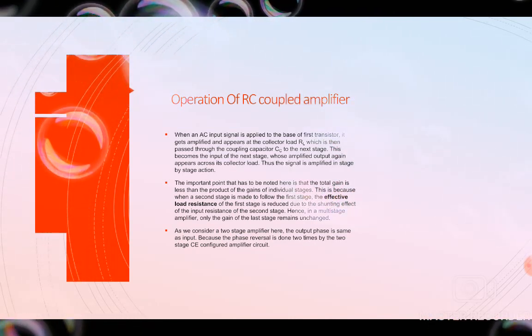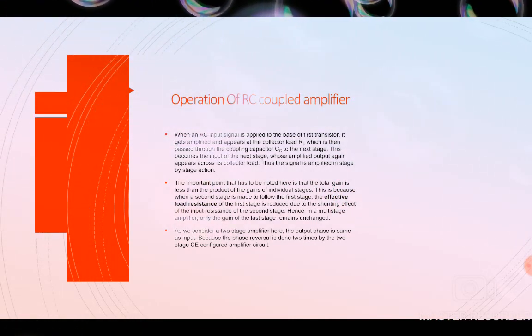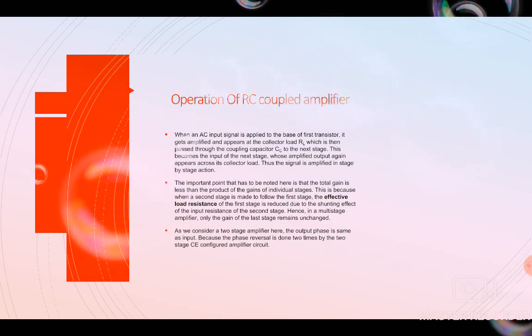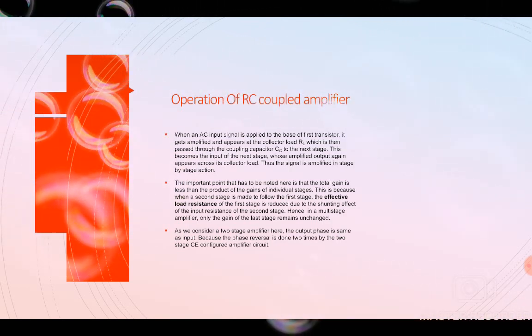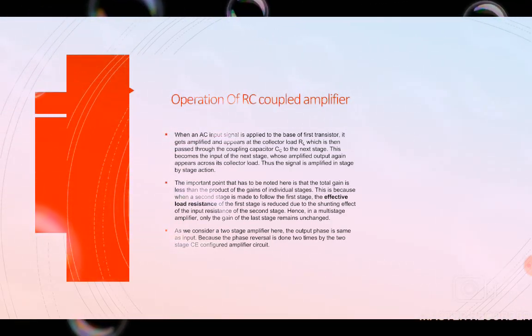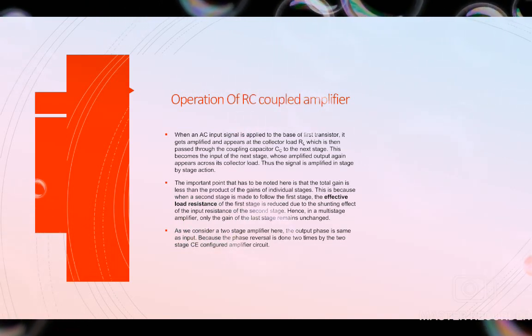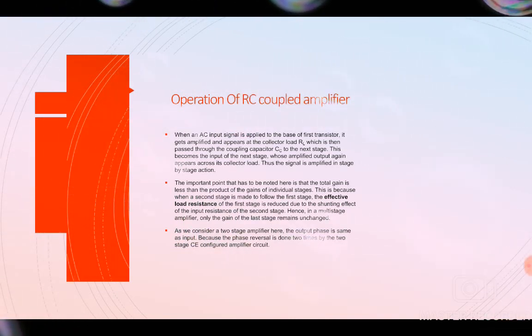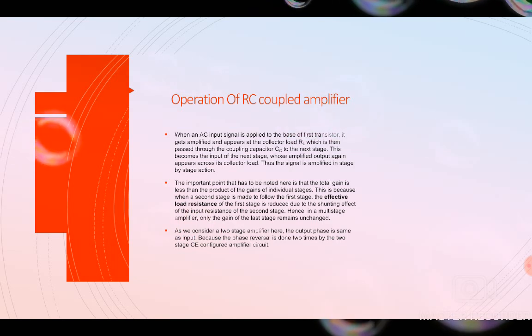As we consider a two-stage amplifier here, the output phase is the same as the input, because the phase reversal is done two times by the two-stage CE configured amplifier circuit.